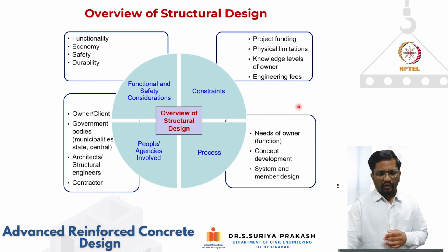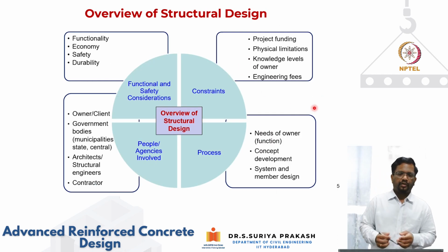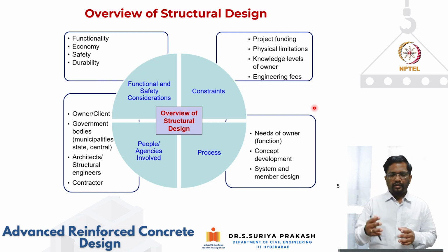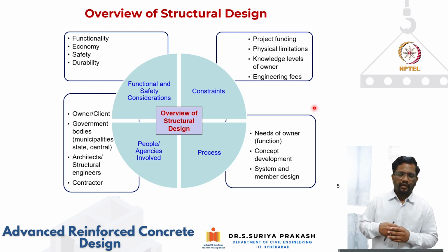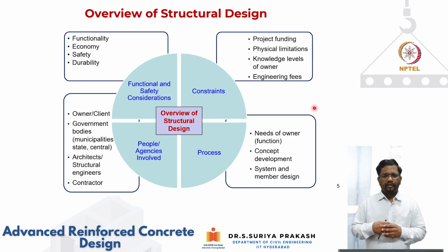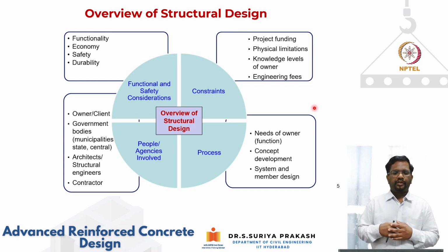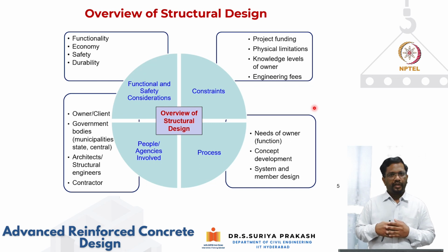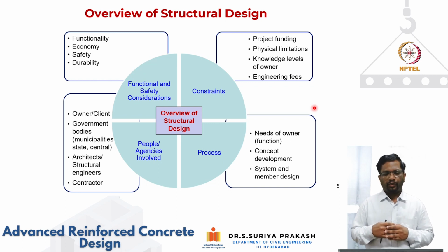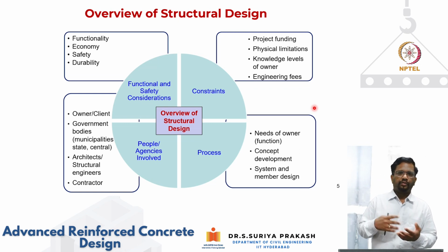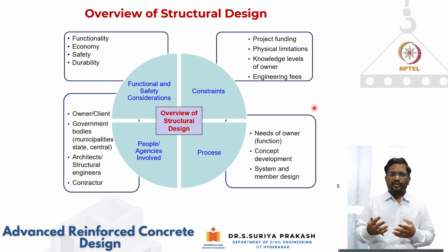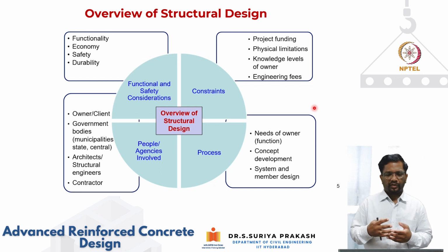Now let's talk about the overview of structural design. In general, the structure should satisfy these four basic criteria when you design. First, it should satisfy the functional and safety considerations, which are very important depending upon what type of structure you are doing. It could be a building, a bridge, or a nuclear reactor. So the functionality and safety of the structural element is the foremost consideration.